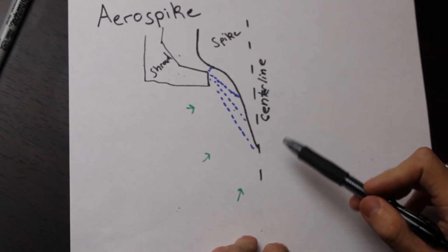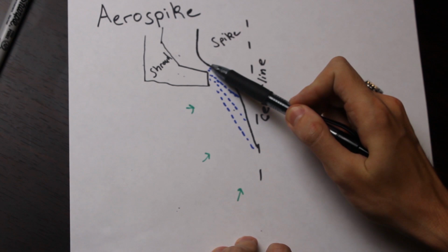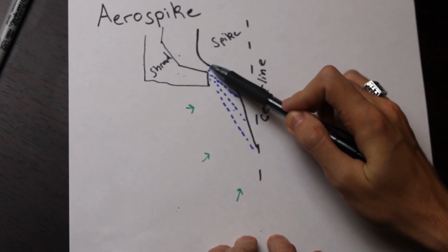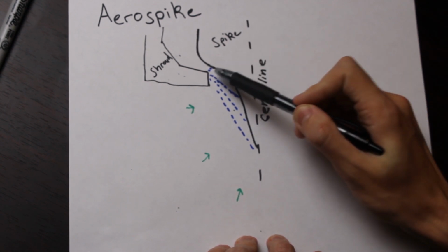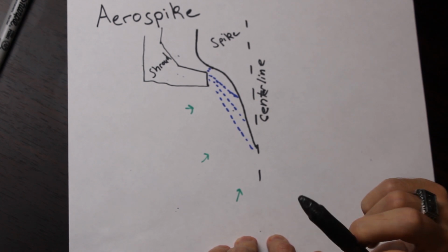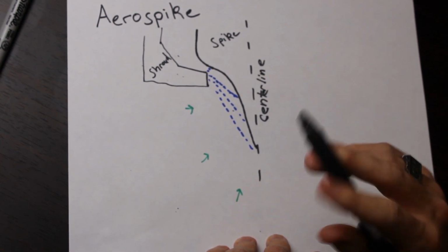Alright, so now looking at our picture, we can find the throat plane. This is the area where the cross-section is the lowest, and therefore the gas will reach Mach 1. We'll assume that we picked this earlier and that we got the right size for the gas to go Mach 1 at the throat. Then, if you notice, right here at this edge of the shroud, we get something that looks a lot like a simple region with an expansion fan, which we already talked about earlier, so we can use all of those analysis tools to help design this.